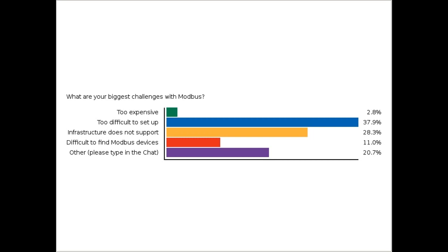Steve says it's less reliable than 4 to 20 mA. On that one, huh, Joe? That's somewhat true. 4 to 20 is an old, reliable standard, and especially with people who are unfamiliar with Modbus, it can be unreliable when problems start to surface. They're hard to fix.